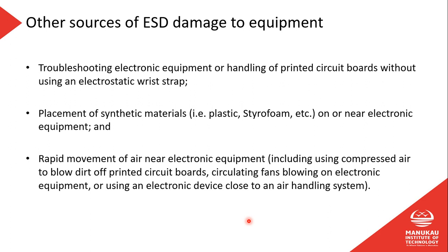Okay, other sources of ESD damage: troubleshooting electronic equipment or handling of printed circuit boards without using an electrostatic wrist strap. Yeah, I mean that's the same. We're discharging the static from our body through the electronic device, but obviously it's more prevalent if you start opening up electronic equipment and handling the boards and the devices, and you're not using an electrostatic wrist strap, then the relative danger of you discharging your static through a sensitive device massively increases, clearly.